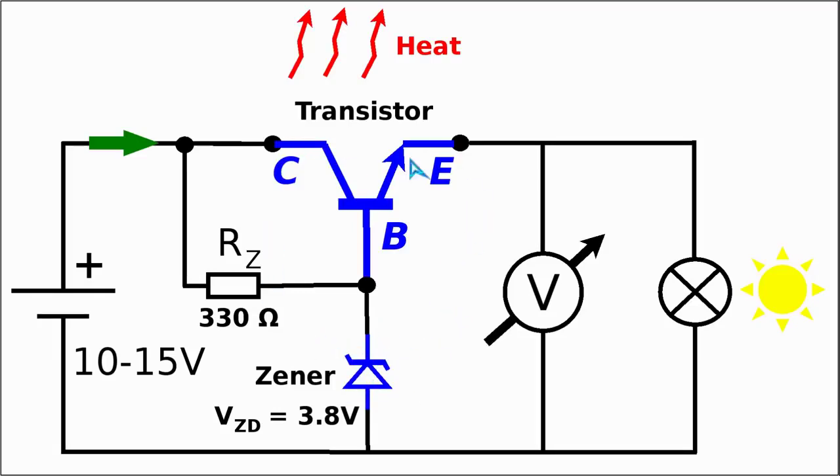After we have identified these components, let us now think about it. Do we have any kind of feedback loop here? The response is no. Okay, then the other question is, are we calculating any kind of error based on the output and the expected value? Again, the response is no. In the current circuit, we are not calculating any kind of error, which means that we cannot provide any type of feedback to our power transistor. And this is the reason why the output will not be stabilized when it comes to this simple circuit.